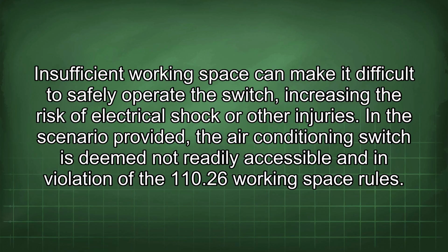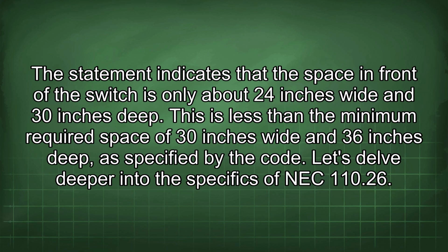injuries. In the scenario provided, the air conditioning switch is deemed not readily accessible and in violation of the 110.26 working space rules. The statement indicates that the space in front of the switch is only about 24 inches wide and 30 inches deep. This is less than the minimum required space of 30 inches wide and 36 inches deep, as specified by the code. Let's delve deeper into the specifics of NEC